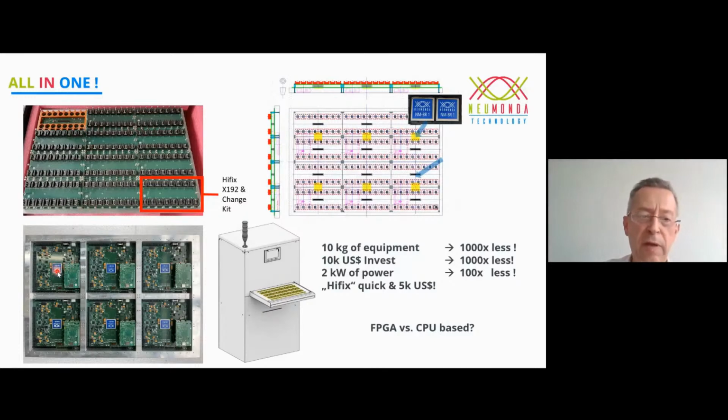In this version here, we use an FPGA to drive the signals. Then you plug the whole board into such a temperature chamber. It moves in, the bottom is cooled. The electronics is protected. The memory components can be exposed to any temperature desired. So you achieve high throughput, almost 200 components you can load, high parallelism, but all are fully operated at gigahertz with all I/O connected.